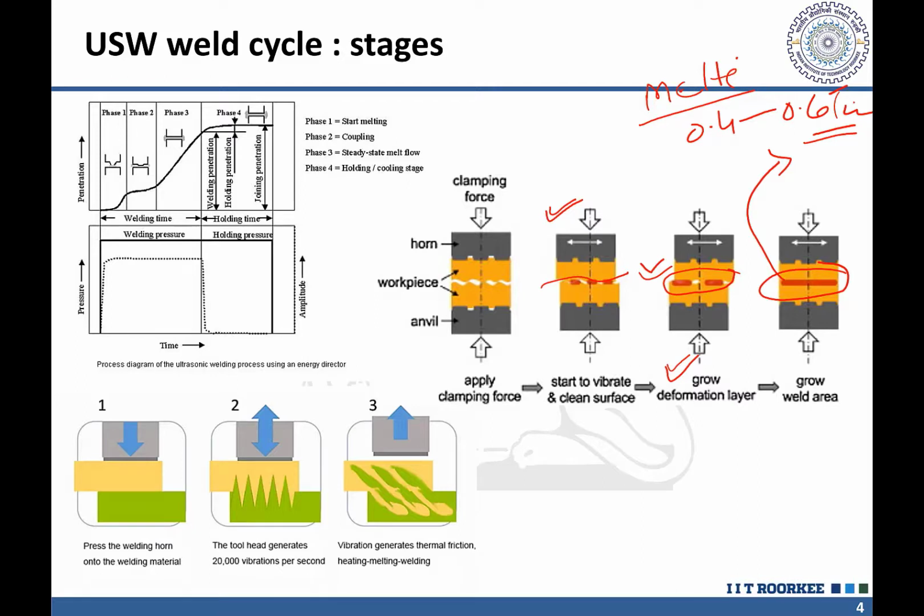Which many times is high enough to facilitate recrystallization, to cause the development of the heat affected zone, recovery and recrystallization, even over tempering, over aging. So those things will also affect the mechanical properties depending upon the condition or the type of the metal.